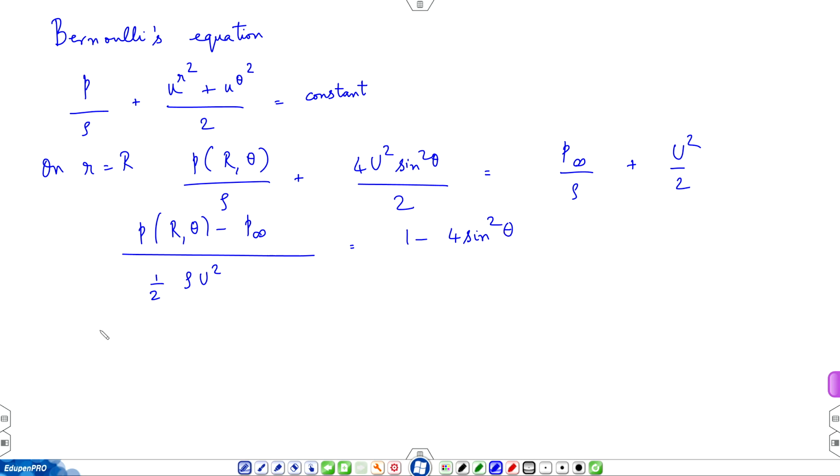And you can get the forces. Forces are obtained by integrating stresses on the surface of the object. There are normal stresses and shear stresses. Shear stresses are 0 because viscosity is 0. Only normal stresses, which at the wall will become equal to pressure in terms of magnitude.